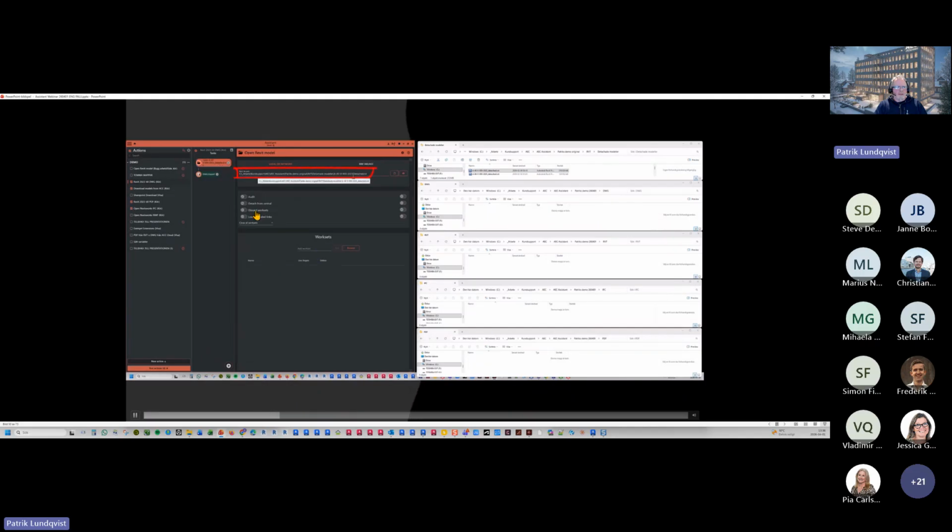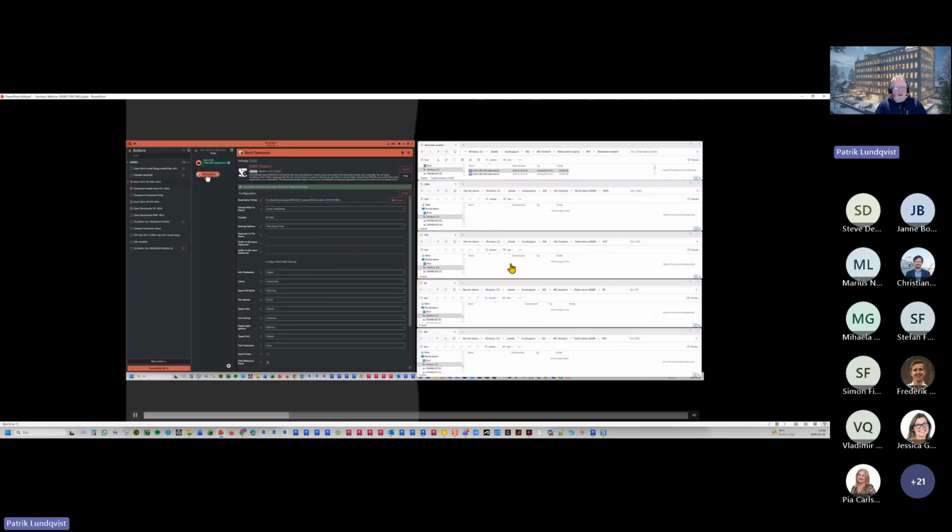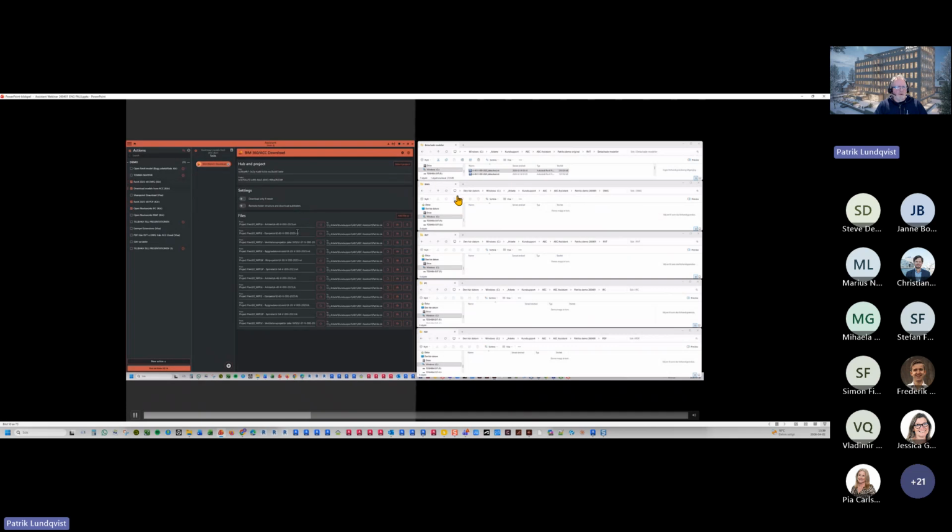So the first one here is the DWG export. It's going to be a 3D exported file, and it's going to end up in the DWG folder here. The configuration I need to do here is actually just tell it what view is going to be exported in 3D and where we want it. And then I've chosen a lot of files from Construction Cloud here to the left, different files, IFCs, RVTs, and told them where they're supposed to go after they're downloaded. So they will go into the RVT folder for the RVTs and the IFC folder here for the IFC files.